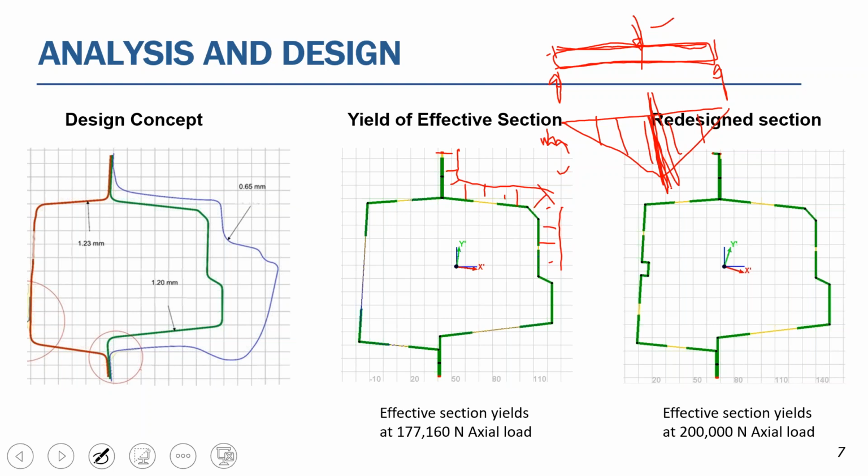Okay. All right. A question saying, can this calculate the force to crush the section? For example, on slide 11, can the section be loaded with a force along the x-axis? Right now, the software does calculate the crumpling load of a stub column, it's called. So it's a short, stocky column.